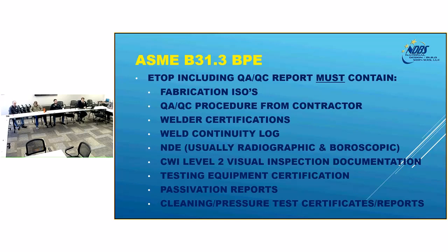So when you're dealing with stainless steel systems, like clean water systems, RO water, USP1, USP2, and WFI water systems, they require cleaning of the stainless steel piping on the inside, because during the course of construction, bacteria or bugs may have gotten in the system, so they use nitric acid or citric acid, and they circulate that through the system, they heat it up, and they kill all the bugs that are inside of that system. And those systems have to be periodically passivated as just a normal course of doing business.